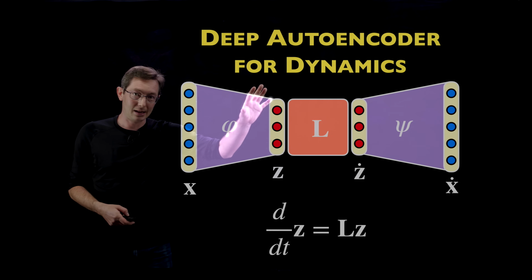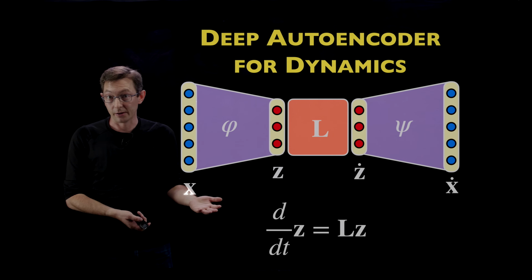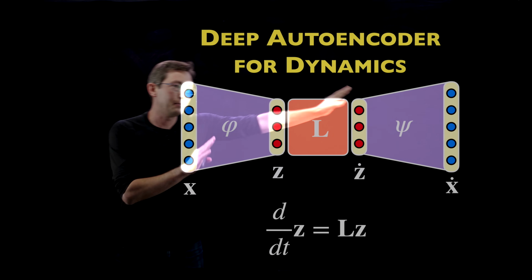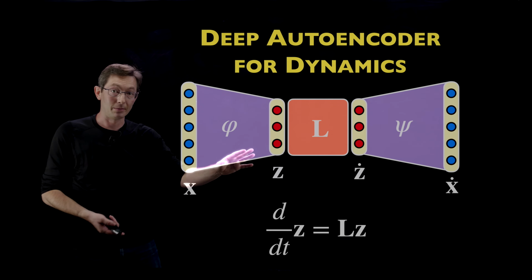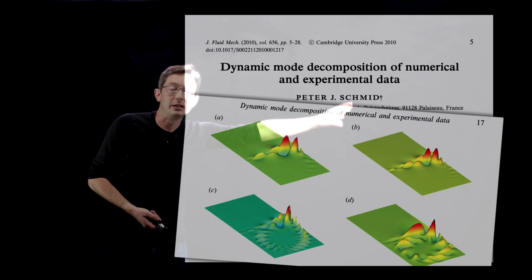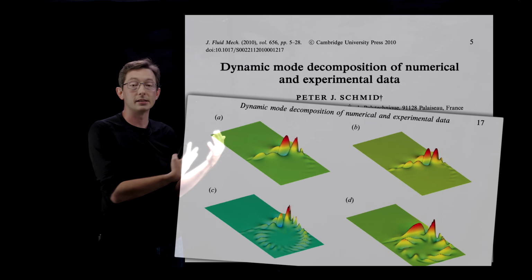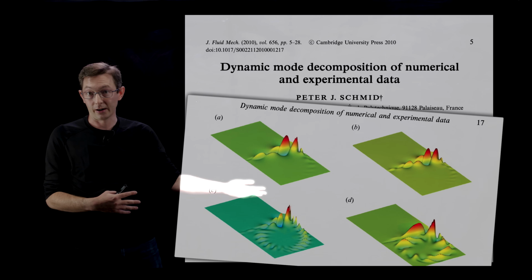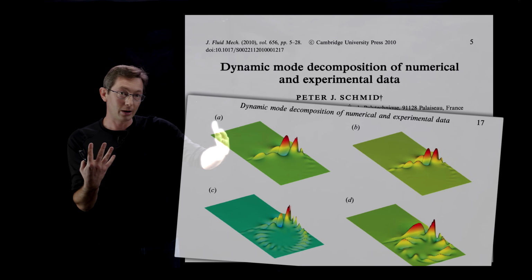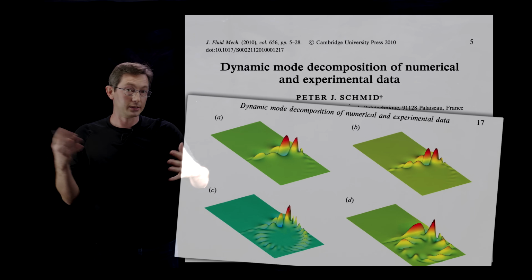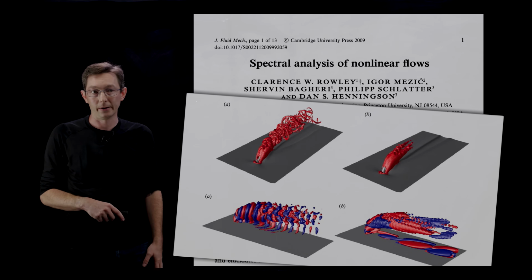In which case, this kind of linear dynamics autoencoder would represent the dynamic mode decomposition. Okay, so if phi and psi were shallow with linear activation units, this would essentially encode the dynamic mode decomposition. So DMD has been used at length in fluid mechanics and many other fields to get linear representations of nonlinear systems like these periodic fluid flows. And essentially, DMD is finding some kind of a linear regression model on those SVD coordinates I talked about earlier. Okay, and there's another cool paper here that connects it to Koopman operator theory.